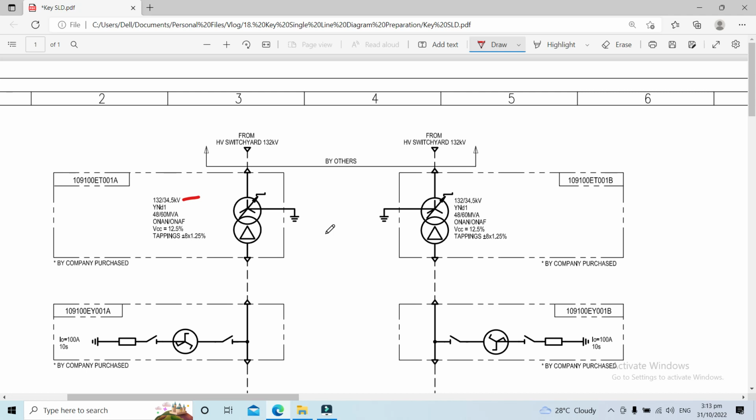They flow round the closed loop of the delta. The delta connection only allows a sinusoidal flux and voltage with no third harmonic in the line. So those are some of the reasons why we make the secondary side delta connected.